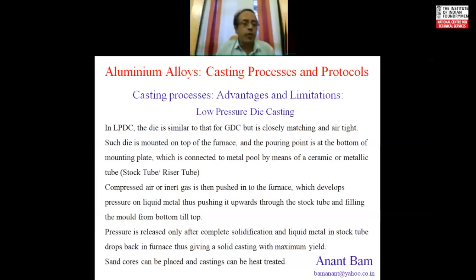Here, one point I forgot to write is that the furnace and the bottom of the die, or the bottom of the mounting plate, all put together make an airtight or pressure tight chamber. And we are putting compressed air or inert gas into that airtight chamber,